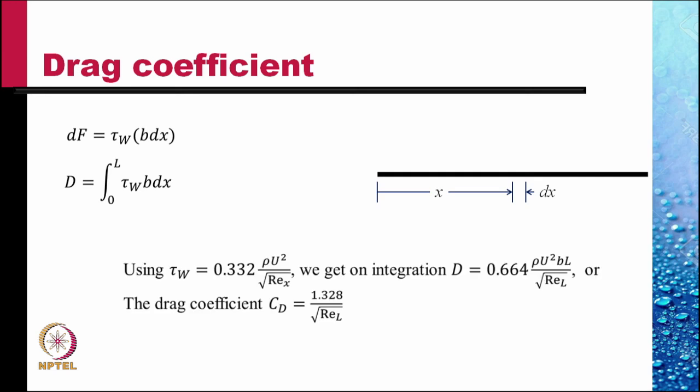And using the expression for the shear stress that we obtained earlier, we get the drag coefficient as 1.328 divided by under root ReL.